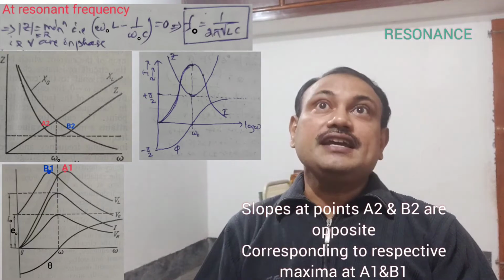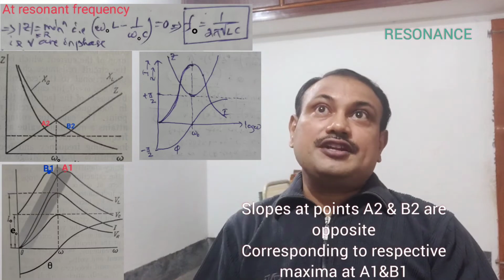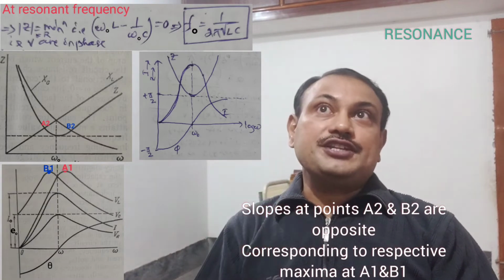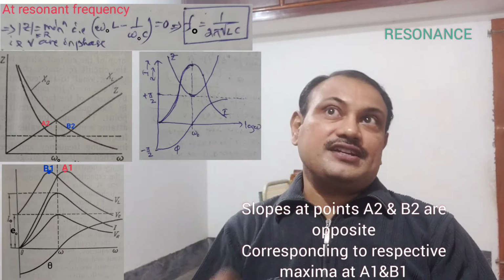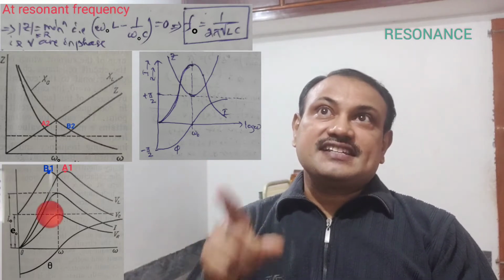It is slightly above the resonant frequency, beyond which this voltage drop falls with a further increase in frequency and becomes equal to the source voltage, that is VL equals E0 at frequency infinity, which again corresponds to an open circuit. And certainly at frequency 0, XL, that is inductive reactance, is 0.